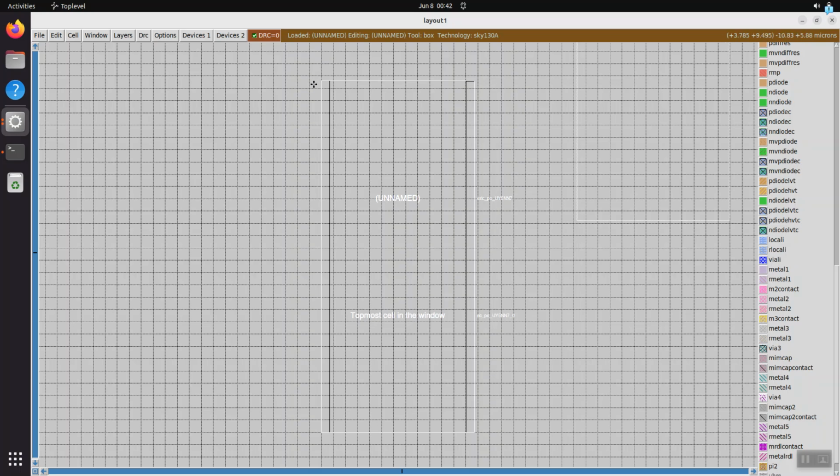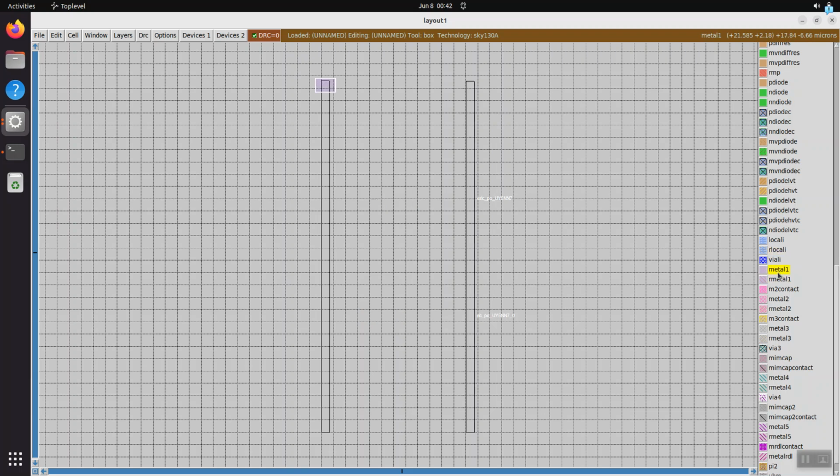So what I'm going to do is just draw. You can see that feature there. I'm just going to draw a box around it and paint it Metal 1. Then I'm going to hover in that box, but not where the resistor is, off to the side. I've selected it. Then I'll come down here where I want it to be. Copy, copy, copy. Because I want the current to flow in here. Then I want it to come up here and flow out here. Okay.